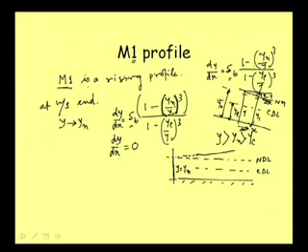Suppose we are increasing the y value, the slope dy dx is 0 here, and dy dx 0 means this gradually varied flow line will meet the normal depth line asymptotically. So, y tends to become yn asymptotically, as we can say from this value, dy dx equal to 0.